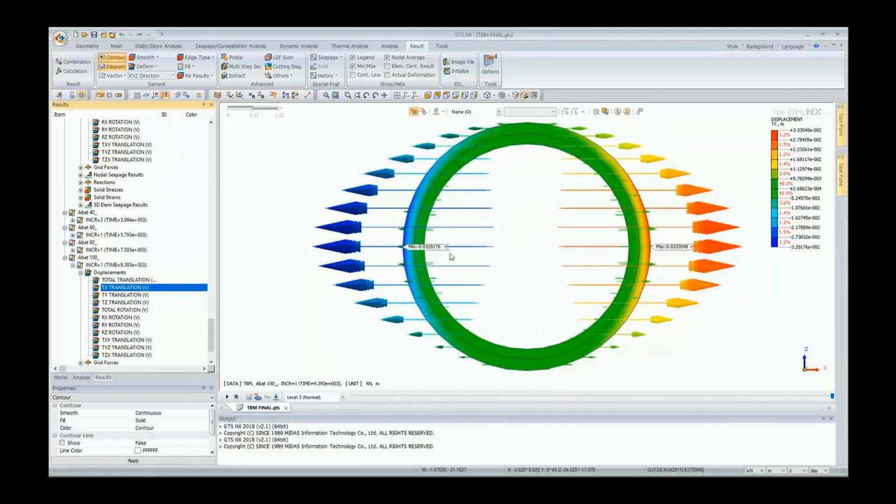So we see here our displacements combined are about 6 centimeters. So we have 3 in the negative, which is left, and 3 in the positive, which is right. So around a little over 6 centimeters. For the local norm in this particular project, the admissible deformation would be 1%.